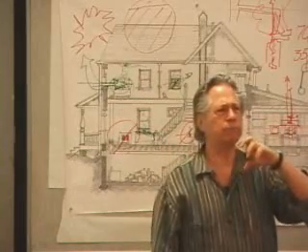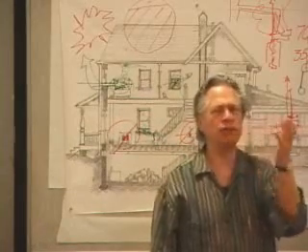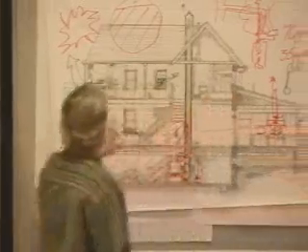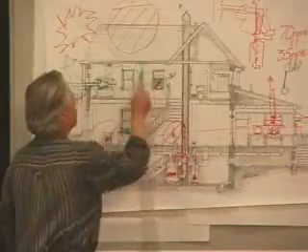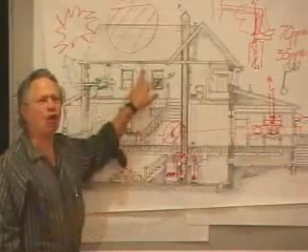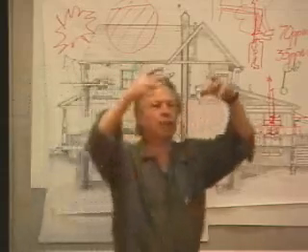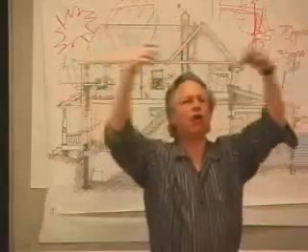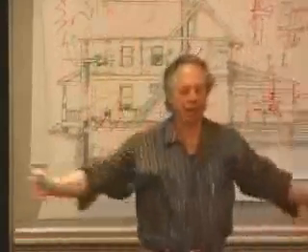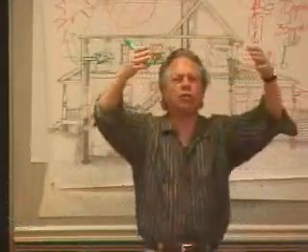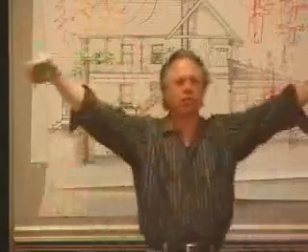How did they do that? How can you do that? The transom, this window right up here, they used to open. They all opened. And so what happens is that you would turn on the attic fan or open up windows at the top, and you would have the cool air coming from the bottom, rising up through the house, going through the transoms, through the bedroom, and out the window. You'd have air circulation in the house.